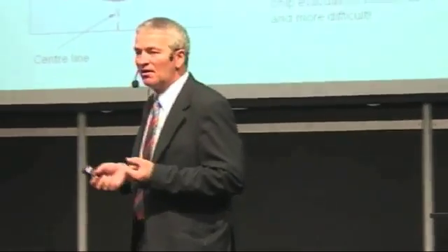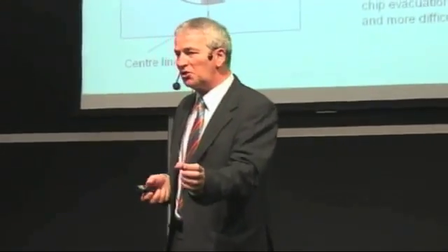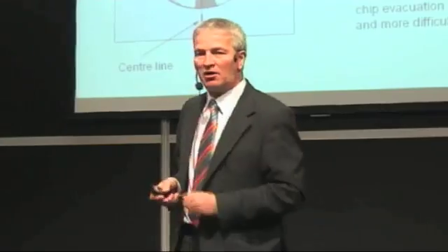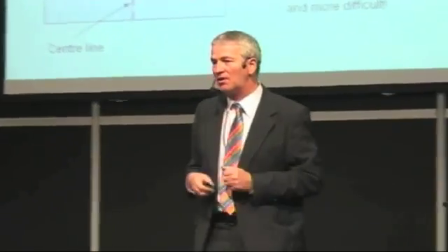So what will be the end? The tool is blocked in the bore, it's welded, you can't get it out, so you have to take a milling cutter to get it out. Or you have to change your drawing of the component and sell the tool along with the component. This is not very often, but could be a solution as well.